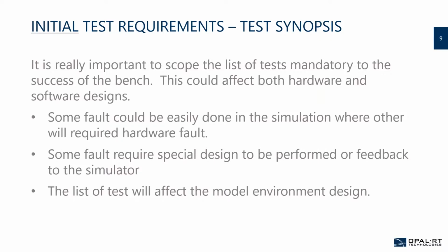Or the hardware that you're going to put in the bench that is related to the aircraft might not also be involved, since usually you don't break a torque motor, for example, for the purpose of a test. You're going to simulate it. So to be able to do that, you need to really think about the faults that you want to do. So the list of tests also will probably define a little bit the environment of the design that you'll be using and where your test bench will be set up.